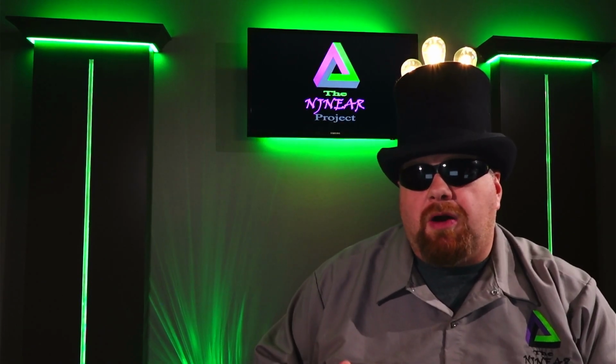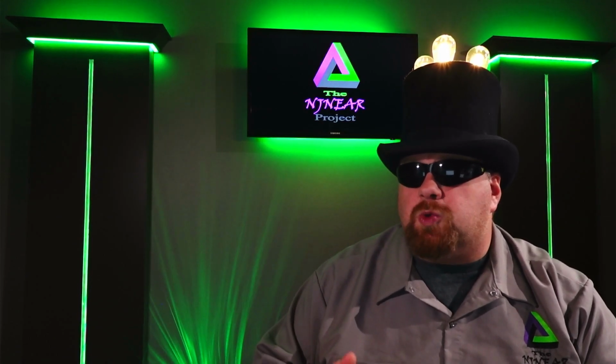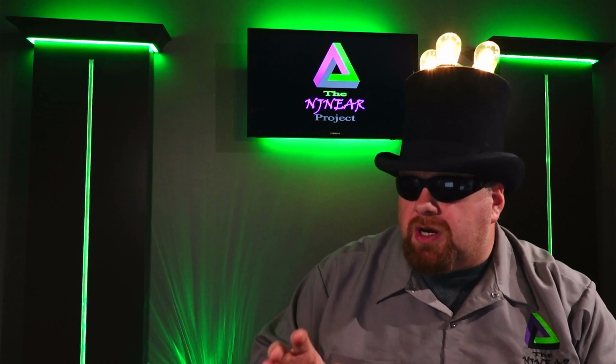I have concerns about combining combusted fuel and steam that would require us to exhaust steam into our atmosphere and therefore increasing our fresh water consumption. So I want to think of this in a pump style and imagine it more like a two-stage pump, one for internal combustion engine process and another for an external combustion engine process. The internal combustion engine will exhaust into a heat recovery steam generator, and then the heat recovery steam generator will operate the external combustion engine through its own cycle. I'll come back to the heat recovery steam generator in a little bit because we're going to break these up.